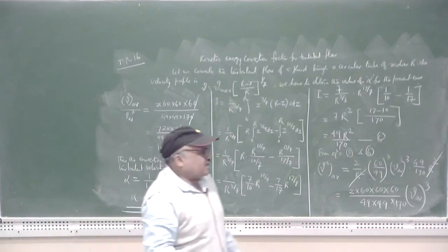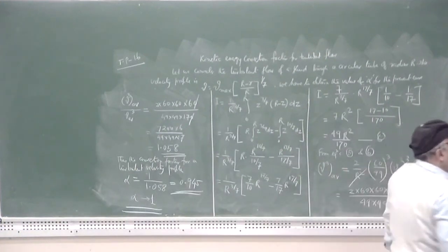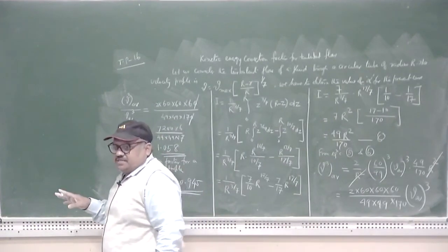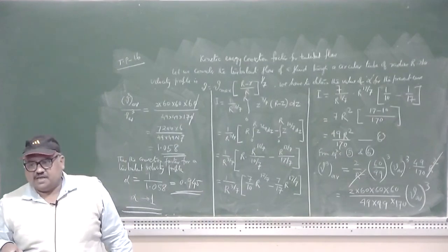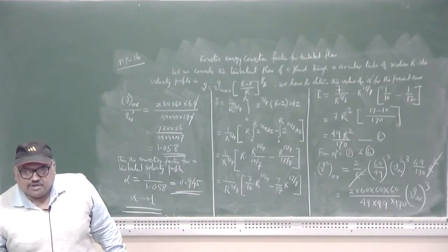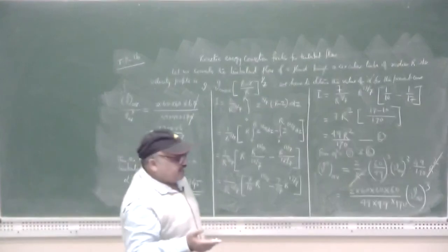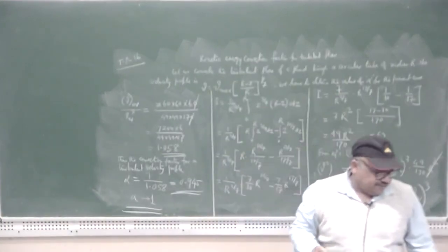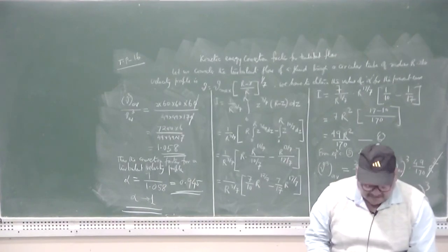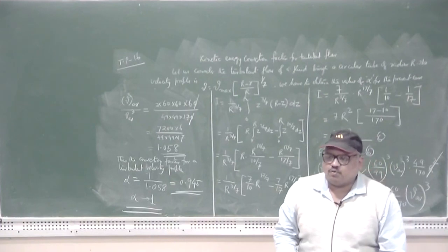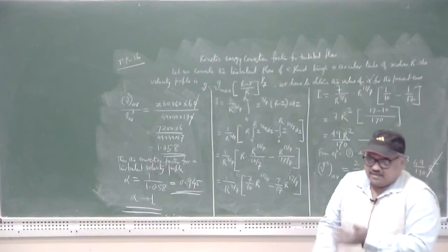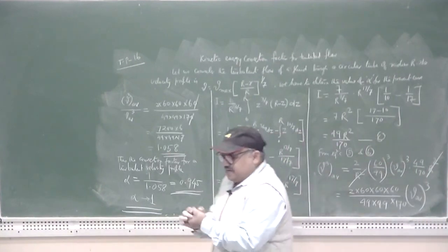So, in the case of turbulent flow, it is often assumed that the kinetic energy velocity correction factor for practical purposes may be assumed to be tending towards unity, whereas in the case of laminar flow, it is advisable that the correction factor be taken as equal to 0.5. So, this completes your kinetic energy correction factor, overall energy balance, etc.